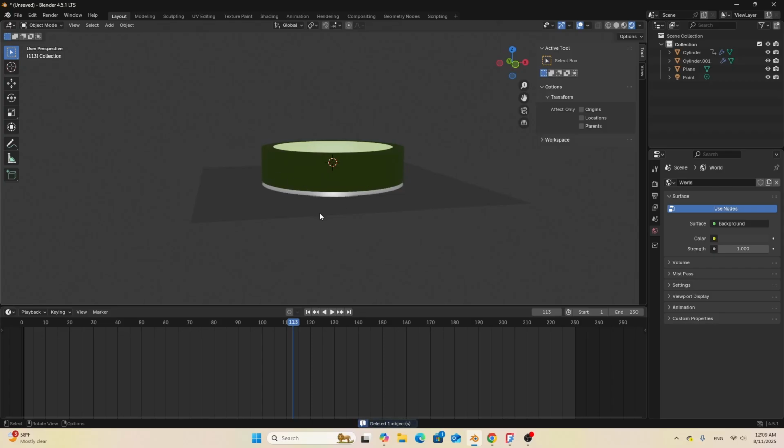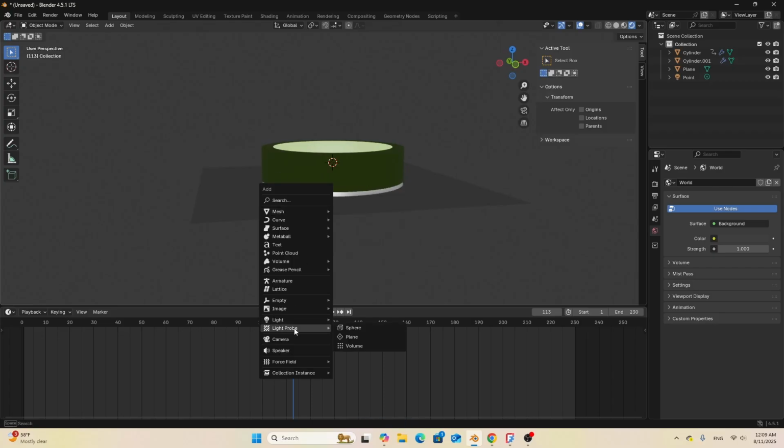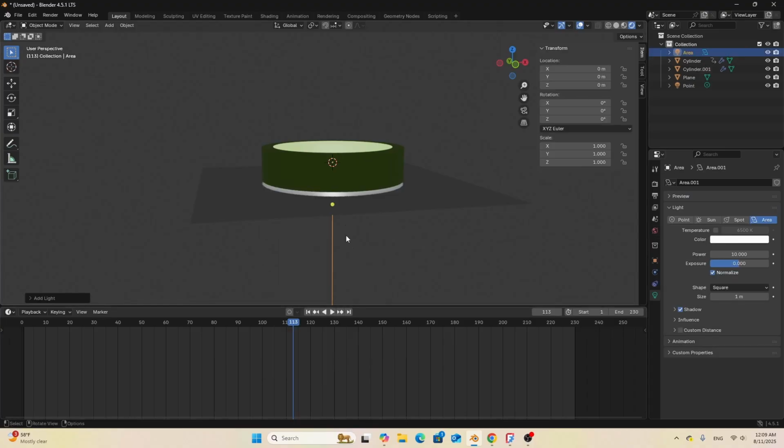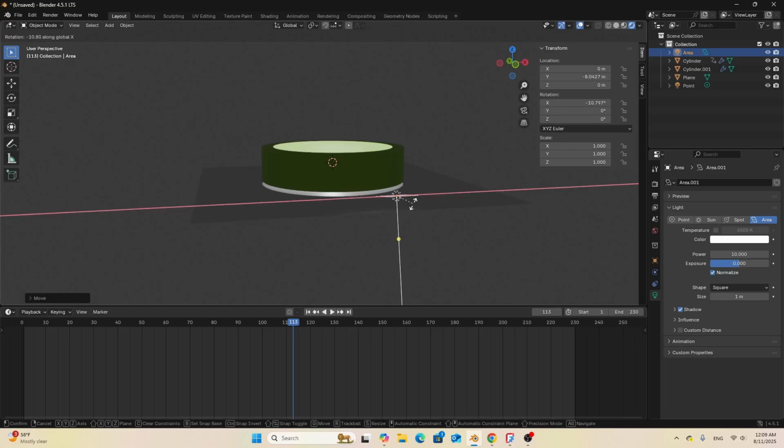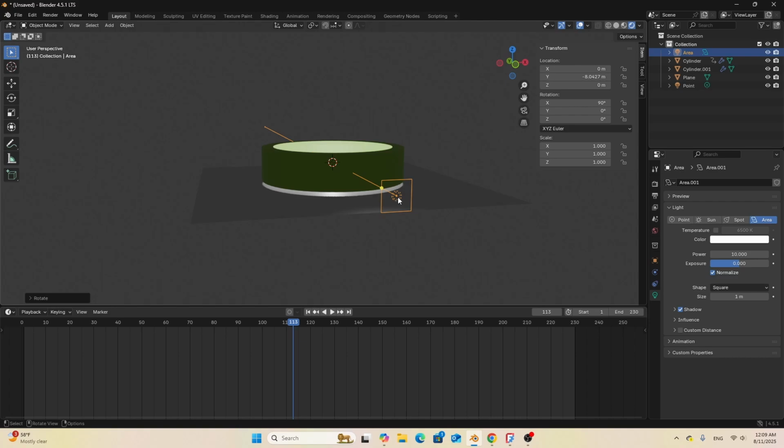I'm going to go ahead and add the surface lights. So I'm gonna add the lights from area, from area 1. Let's grab it. Grab the light and Y, move it outward. That's good. And then we're going to rotate, R, and we're gonna rotate again on the X-axis. Go 90 degrees. That's good. I'll try to move a little bit closer. Grab Y and go closer.